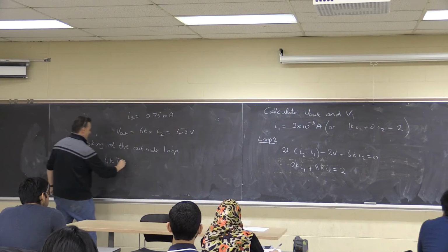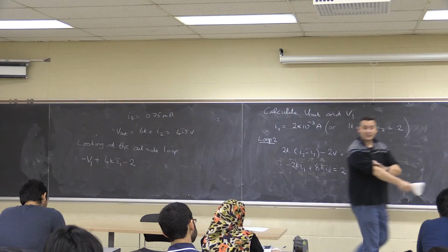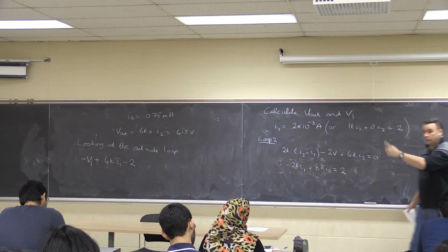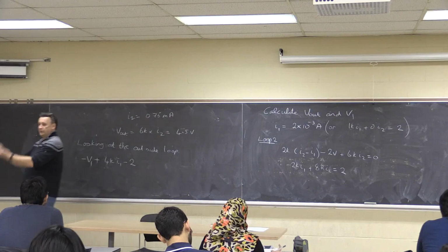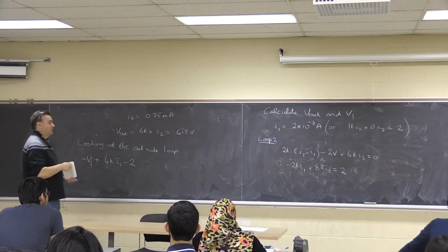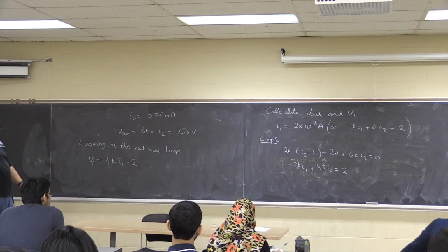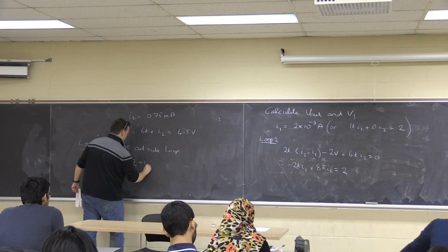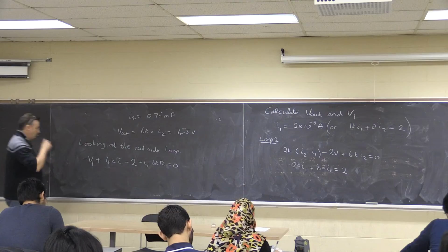Well, no, it's just -2. The other side of the board is confusing, but if I go through here, I know the voltage change is -2 in my convention, because I'm going around the loop with the current, I'm calling voltage increases negative and decreases positive. Or I can write an equation with increases at one side and decreases at the other side, if that's clearer. Voltage change across the 6K resistor, well, we know that already, it's just plus I2 times 6 kilo ohms. All that equals 0.